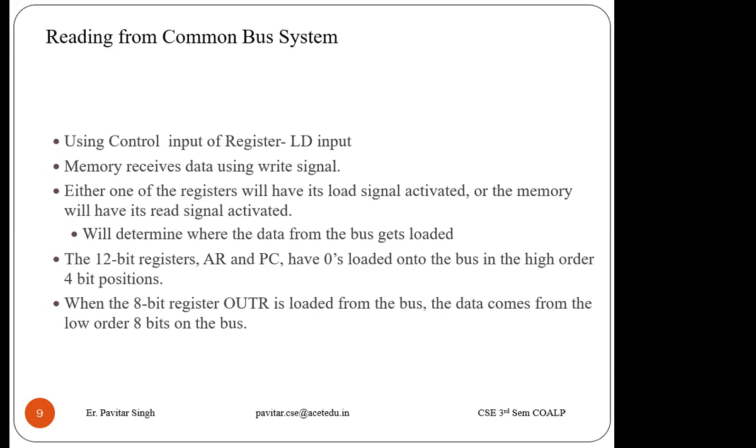Similarly, INPR takes the input from the keyboard and receives only 8 bits, right? And OUTR gives the output to the monitor to display 8-bit characters. The other 8 MSBs will be 0 in the case of these two registers, right?